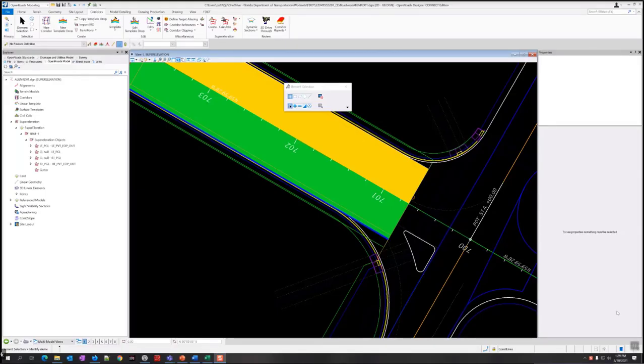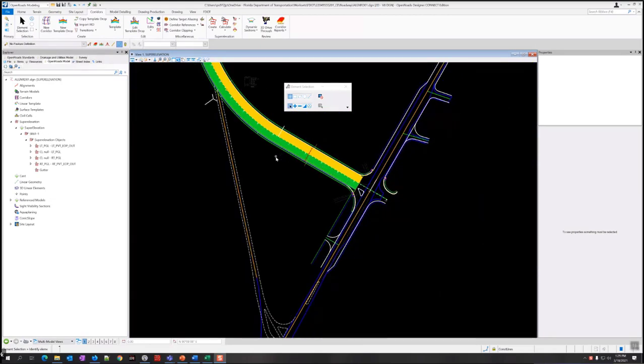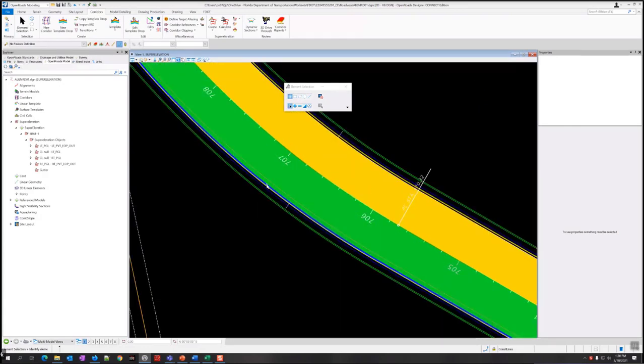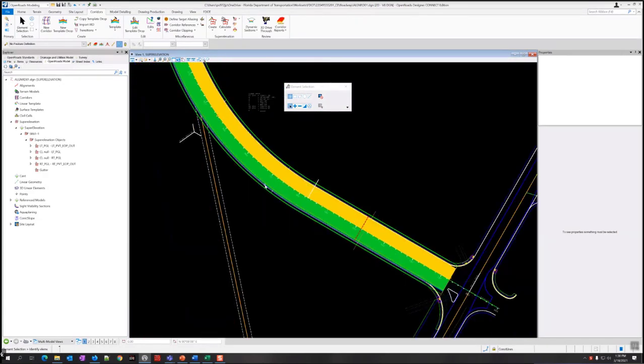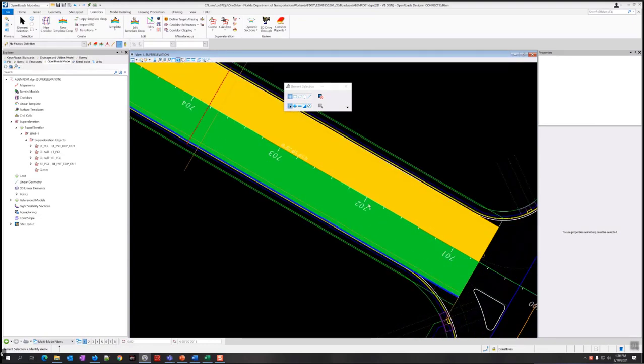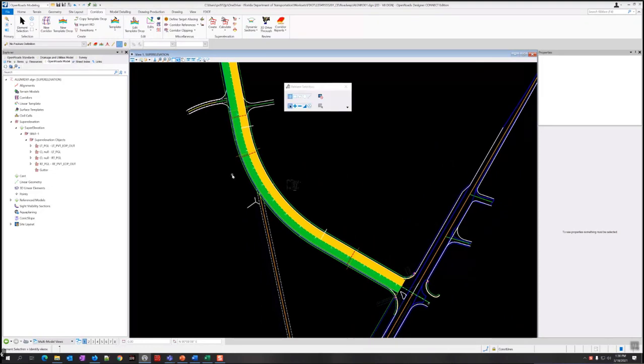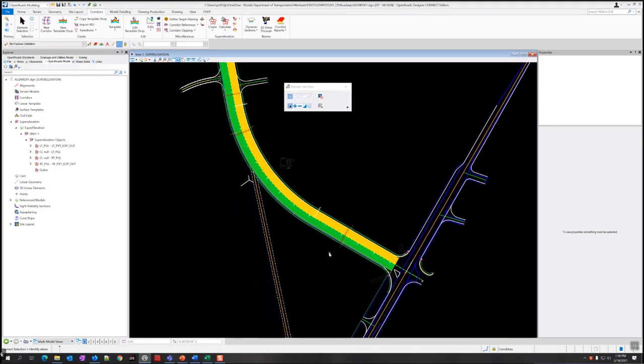All right, so we have the super elevation shapes. We had calculated it, and now we removed the super elevation because we manually added this curb and gutter shape, so that this can be treated like a lane and transition as well. So now we need to calculate it again, including this gutter shape. We have a starting point, and that mostly follows the transition.